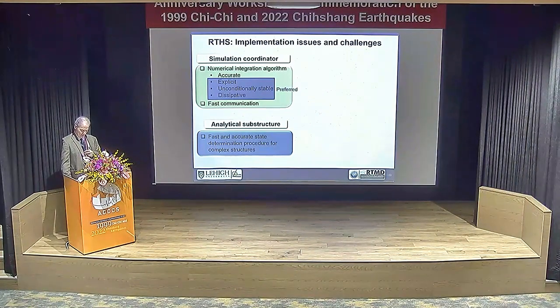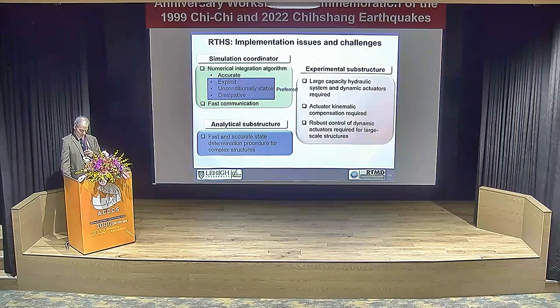You can't fit it into your lab, so you have to consider what to put where. And then on the experimental substructure, you really should try to do it as large as possible so that you don't have scaling effects, and that requires servo-hydraulic power. This is usually where specialized laboratories, like ours, have a novelty, so I try to convince people to come visit us. We have the novelty to do this, but you have to have large hydraulic equipment.